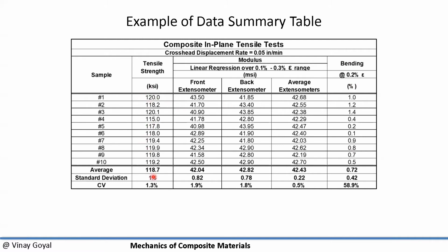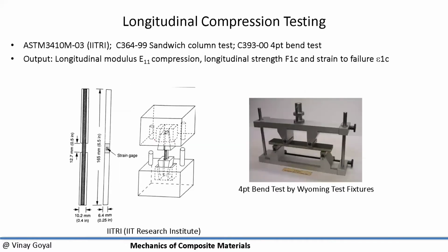And here you can see the tensile strength. There's an average value you can calculate, and then we have the standard deviation. Those two may be needed later in the calculation. I need to come up with an approach to calculating the allowables later. But again, this piece of information is highly important. We have to calculate the tensile modulus and the tensile strength, and they both become important. One can make an argument that this looks out of family, potentially. We don't know until we do statistics.